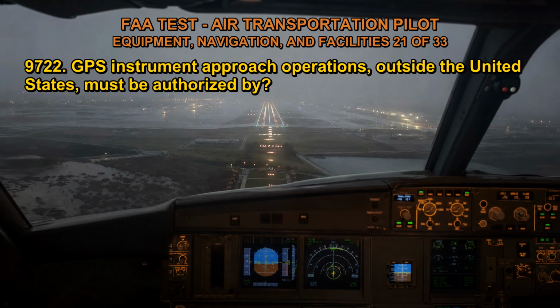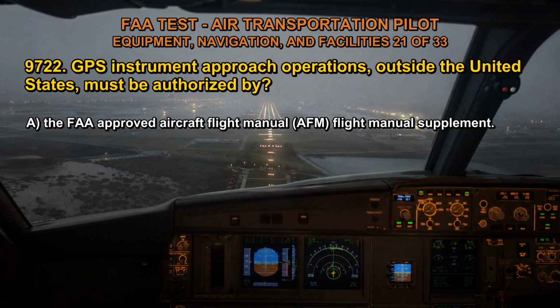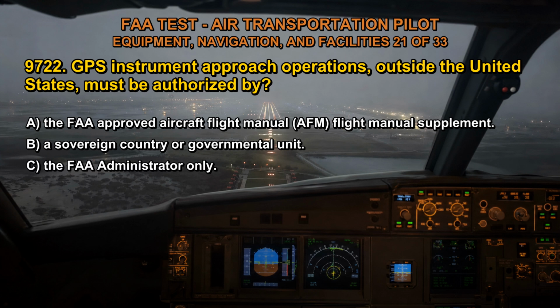9722. GPS instrument approach operations outside the United States must be authorized by A. The FAA-approved Aircraft Flight Manual, AFM, Flight Manual Supplement. B. A sovereign country or governmental unit. C. The FAA administrator only.